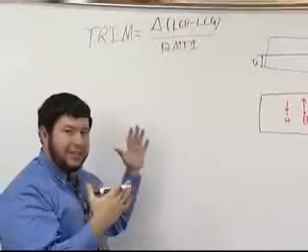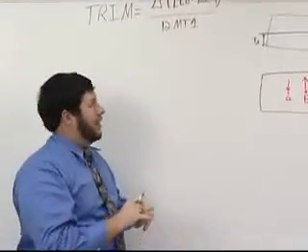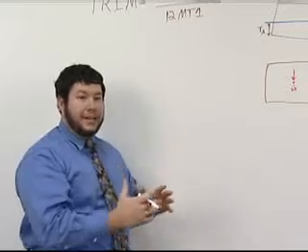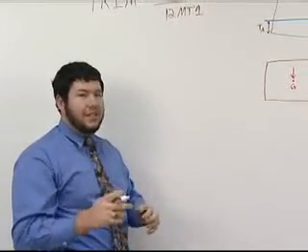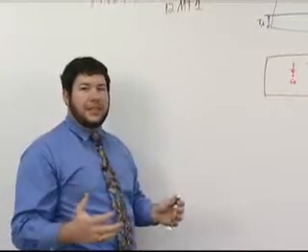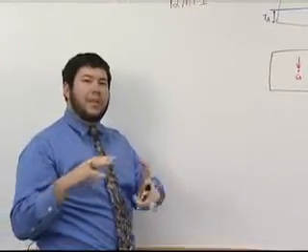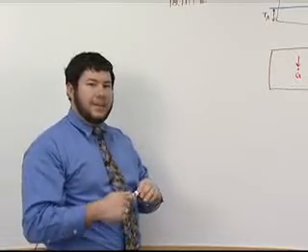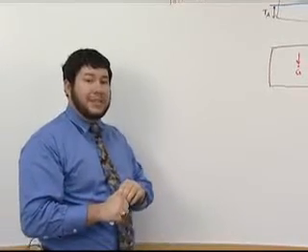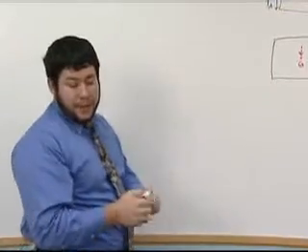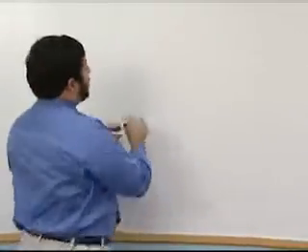Trim is listed in terms of feet, but we calculate the moment to trim 1 inch, which we'll do now, in terms of inches. And that's a convention based on the fact that generally it makes more sense. The numbers are more manageable for ships. In your instance, the trim will probably be measured in inches, so it'll also be pretty manageable for you that way.